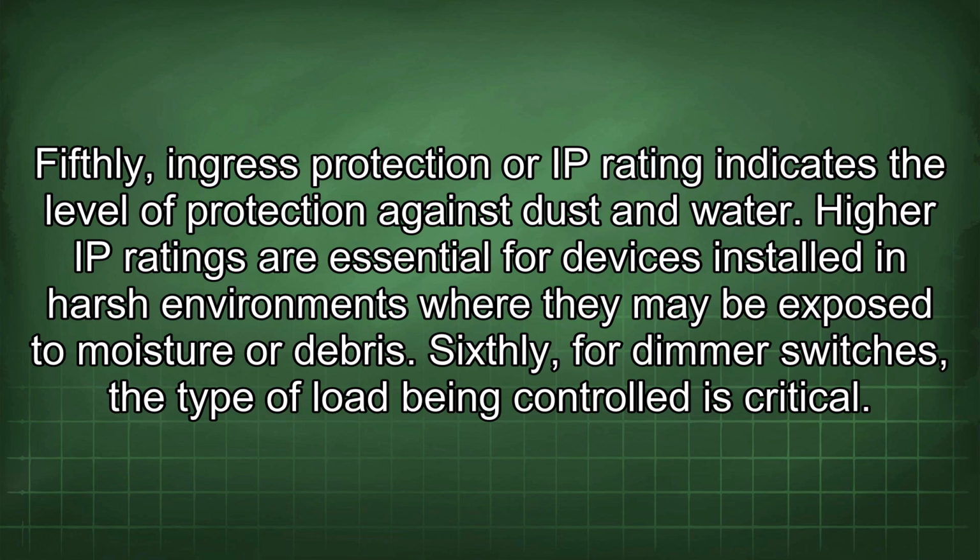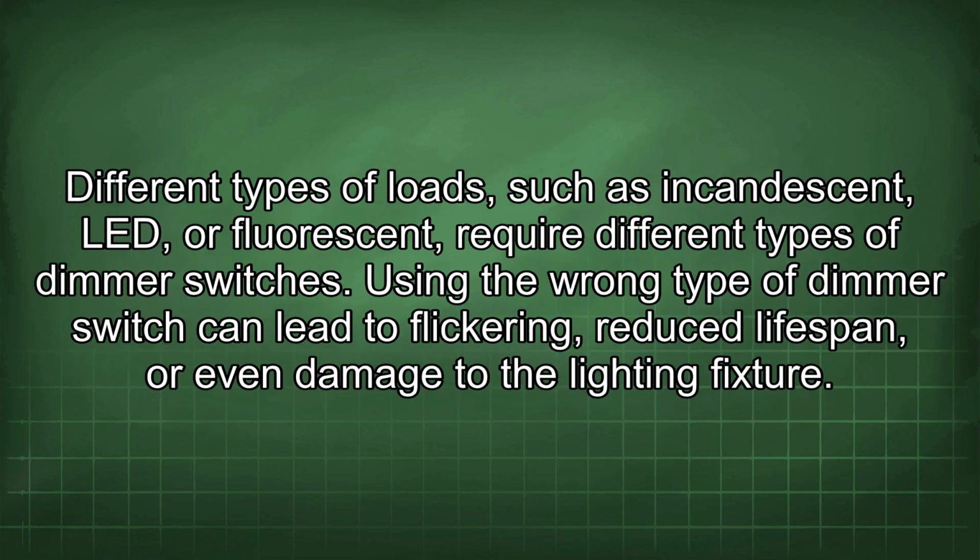Sixthly, for dimmer switches, the type of load being controlled is critical. Different types of loads, such as incandescent, LED, or fluorescent, require different types of dimmer switches. Using the wrong type of dimmer switch can lead to flickering, reduced lifespan, or even damage to the lighting fixture.